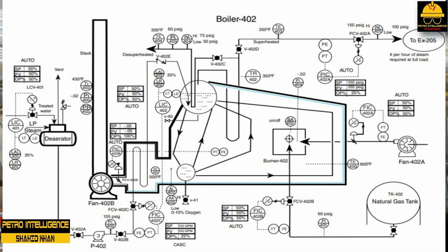B402 is designed to operate at 120 psig. However, some operating facilities require low-pressure steam. This is when desuperheating is used.